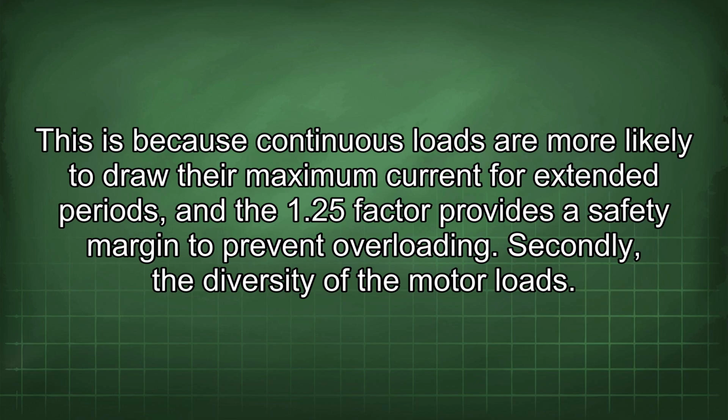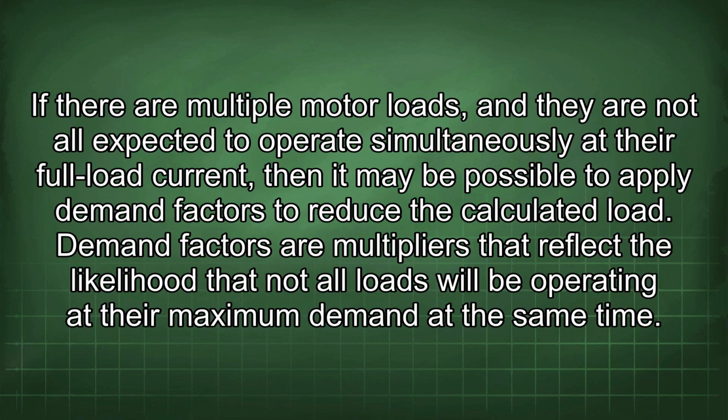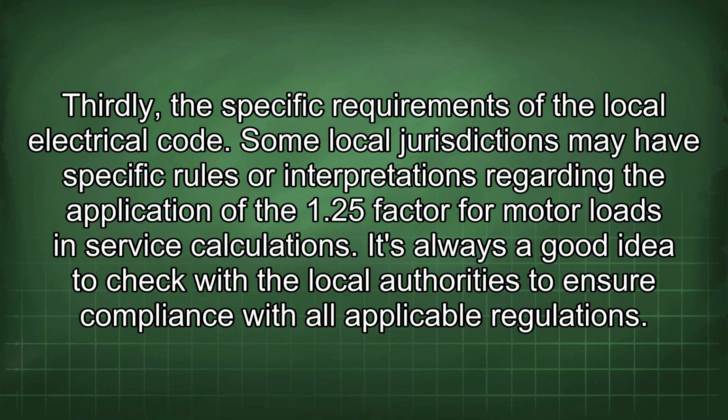Secondly, the diversity of the motor loads. If there are multiple motor loads, and they are not all expected to operate simultaneously at their full load current, then it may be possible to apply demand factors to reduce the calculated load. Demand factors are multipliers that reflect the likelihood that not all loads will be operating at their maximum demand at the same time. Thirdly, the specific requirements of the local electrical code.